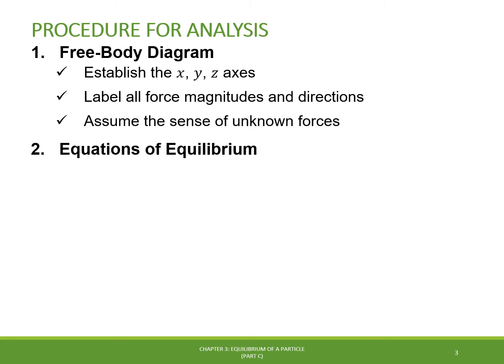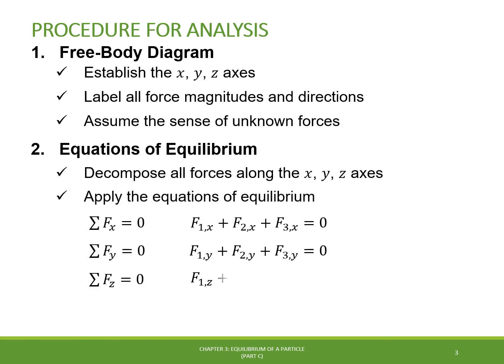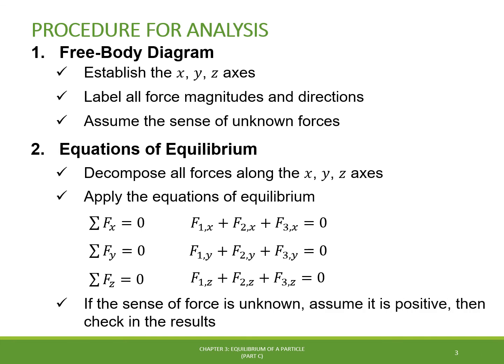Then we have to turn our attention to the equations of equilibrium, in which we first decompose all forces along the x, y, and z axis, apply the scalar equations for equilibrium for each direction, and finally, for the calculation of the forces, we initially assume that they are positive or oriented through the positive direction of the respective axis, and check if it's correct after we get the results.